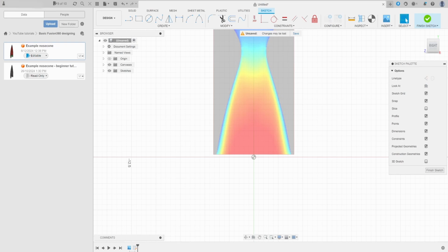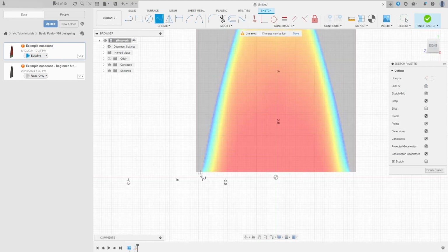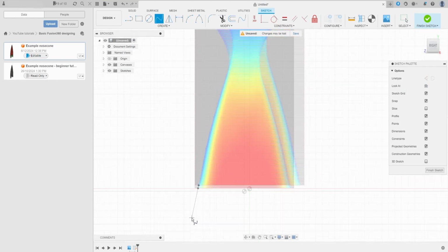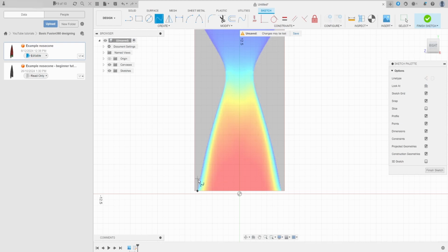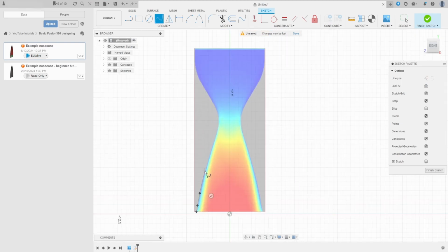Now we're going to mirror a line from our image to make it so that we can revolve. I'll select Fit Point Spline up here in the Create menu. Now, you can just generally select a rough area and then you can make it however accurate you want. This depends on how many points you actually place. I'm going to place a few points along the line of this image.